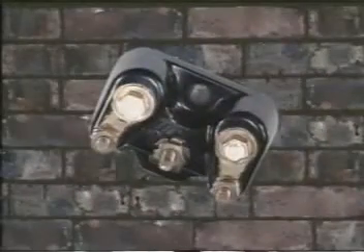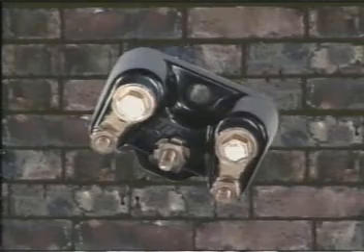Well, the customer has a telephone line in their facilities, whether that's in their house or in their business. That line is called inside wiring and it belongs to the customer. At some point, it comes out of the building and it attaches to the network at an interface device. Very often, that interface device was a set of carbon blocks that were mounted on the outside of the building, and these carbon blocks had two lugs on them, and the two wires of the telephone were connected to the two wires of the network. This provided the interconnection. As telecommunications devices have become more complex, we find that we require much more protection and much more sophistication in our interface.